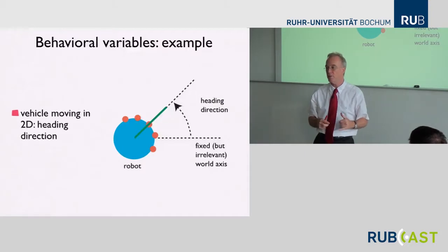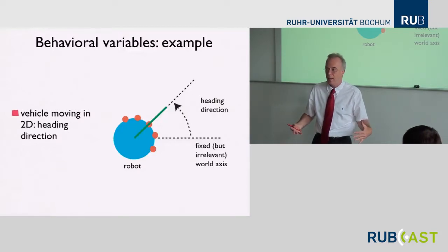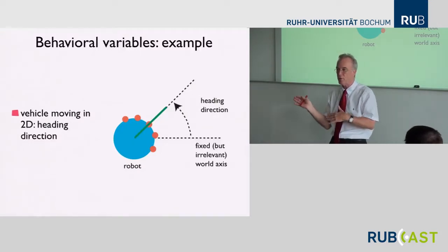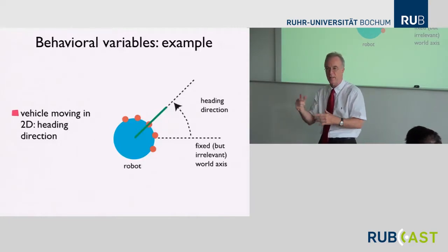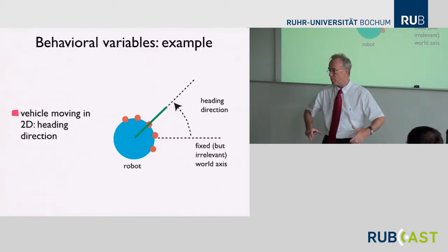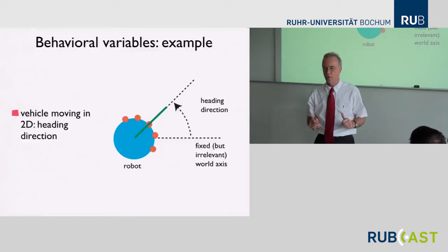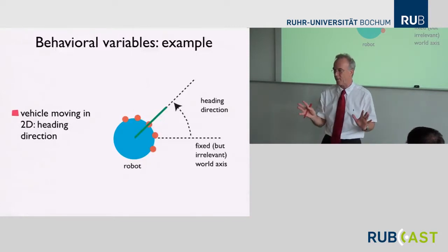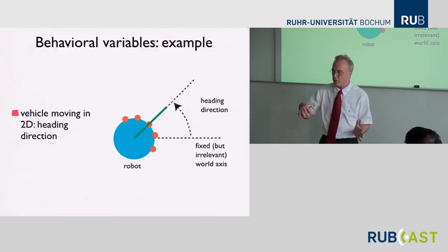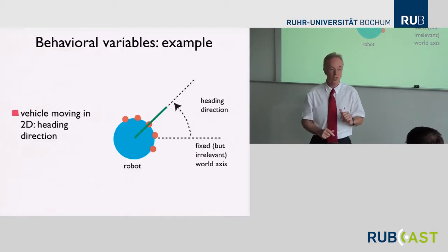And moving around in 2D means giving the control signals to the 2 wheels. So in that sense, we have 2 degrees of freedom. And I'll neglect 1 and just talk about 1 degree of freedom, namely just the heading direction of that vehicle. The heading direction is controlled by giving a difference in command to the 2 wheels. The average command is the forward speed of the robot along its path, and I'll just assume it's constant for now. In our actual robot models, of course, we also give some design for that, but I'll just neglect that. It can be separated out. So this vehicle is moving at constant forward speed, but by giving these differential commands, it can make any kind of change to heading direction.